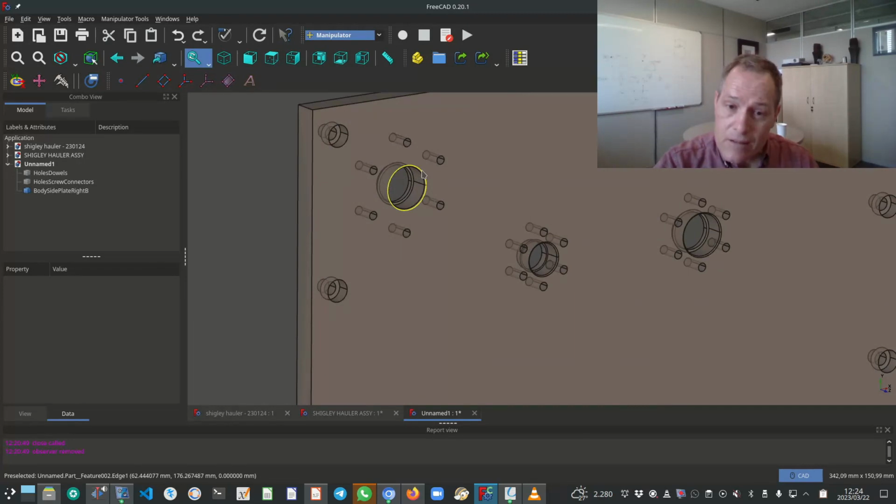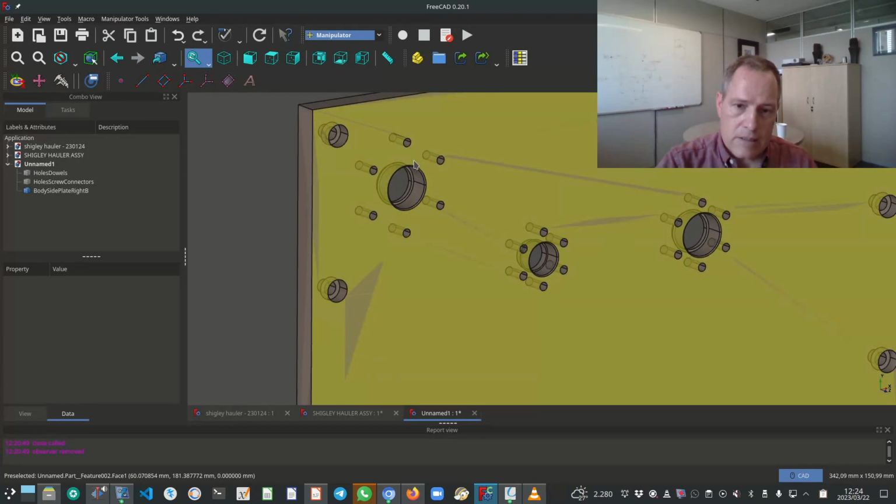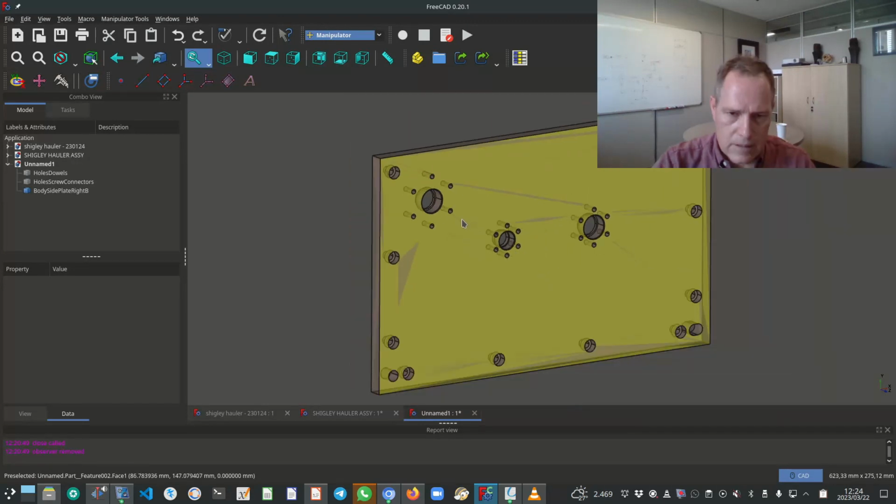The diameter of that hole, we can measure again as before with the caliper. I'm not going to show that again. The tolerance of that hole is very important. So you need to select the letter and the number for the tolerance value of that hole. That you need to do. Now, that's straightforward.